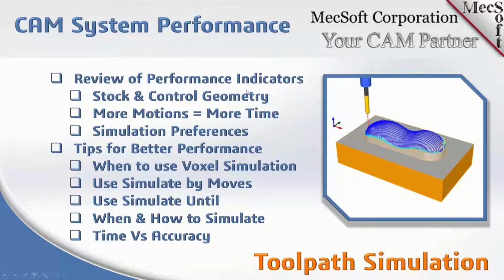What are the performance indicators for simulation? Obviously, it's your geometry, the stock model, the size of your stock, your control geometry, your containment area. How large of an area are you cutting or simulating? You can think of it simply as more motions, more time. The more times that tool moves from point A to point B, the more time it takes to simulate. But there's a way around that, and we're going to show you that trick in a minute.